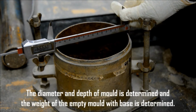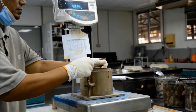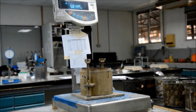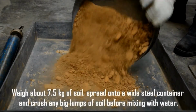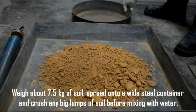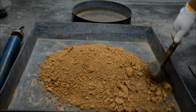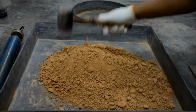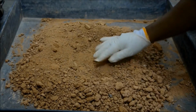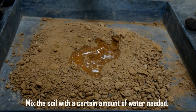Procedure. The diameter and depth of mold is determined, and the weight of the empty mold with base is determined. Weigh about 7.5 kg of soil, spread onto a wide steel container and crush any big lumps of soil, before mixing with water. Mix the soil with the amount of water needed.